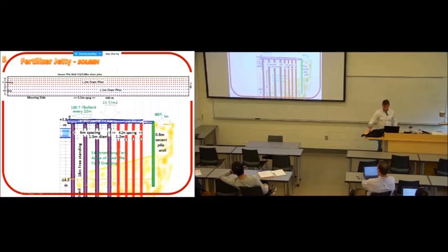And some more data about the geometry. This is how the piles are going to be. Front row piles, four rows, 1.5 meter diameter. The back rows, 1.2 meter diameter. Spacing between them is 5.5 meters in the longitudinal direction, parallel to the ocean. And then perpendicularly, it goes from 6 to 4.2 meters.